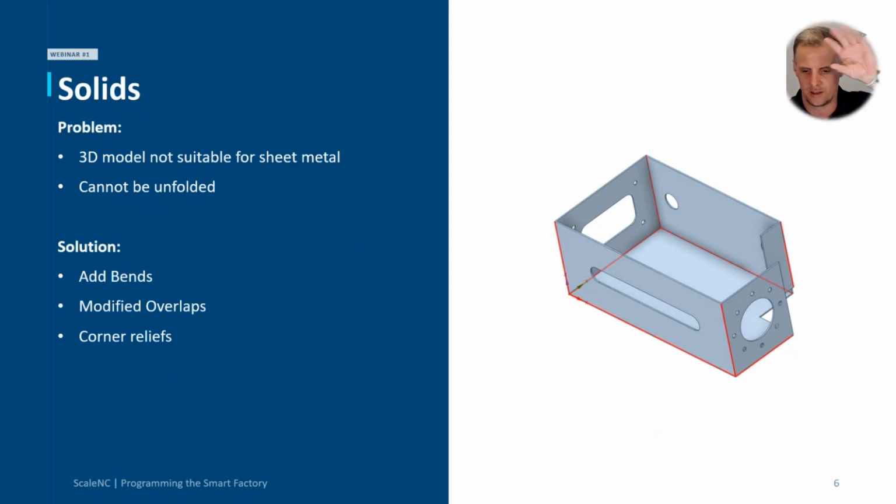I added and modified the overlap, and also the corner reliefs were created automatically, and everything I did, overlaps, corner reliefs, were adjustable afterwards.